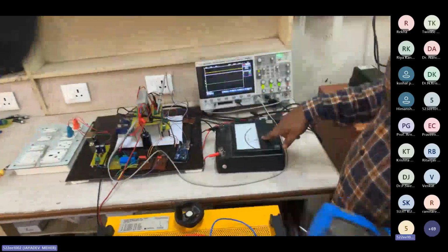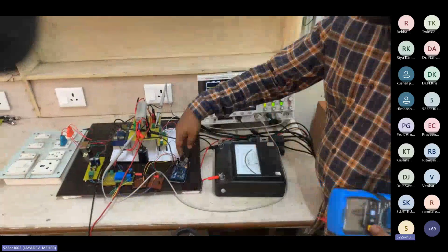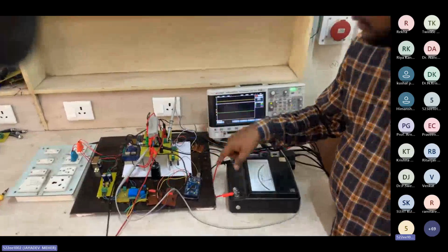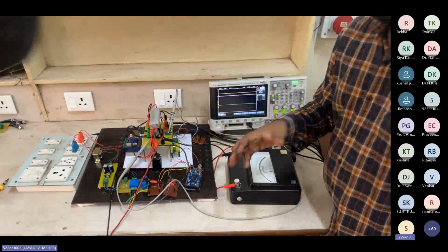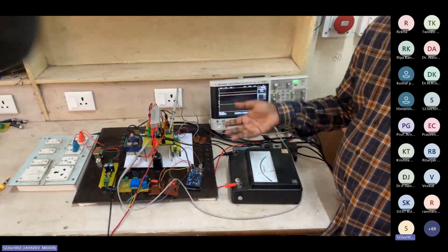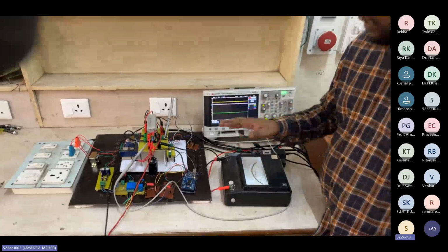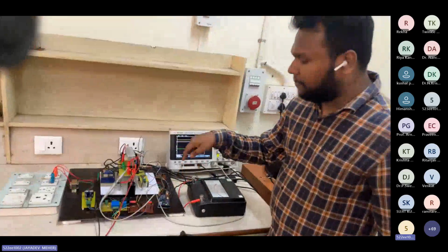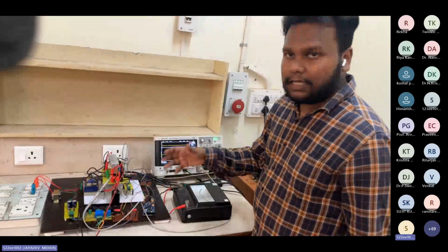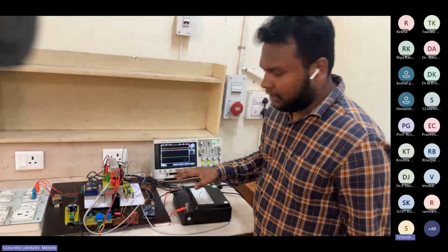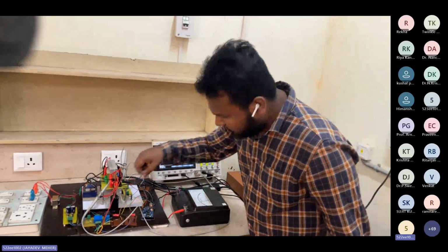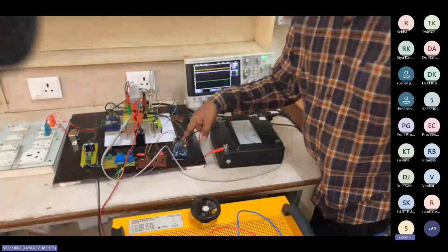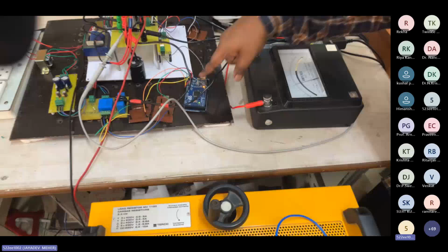I have to tell you about this. This is the Arduino Mega. In this Arduino you have to put the P and O technique, PSO technique, or any fuzzy technique, any technique you want to control with. I built the P and O technique in the Arduino Mega. A0 and A1 are the inputs: A0 is the VPV and A1 is the IPV.